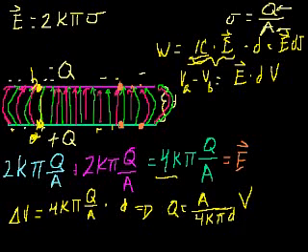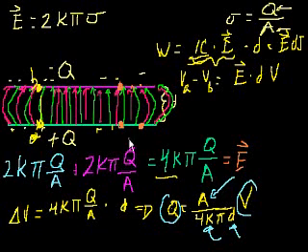Well, what it shows you is, if we assume that the area of the plates isn't changing, that's a constant. This is definitely a constant. And if we assume that the distance between the plates doesn't change, we see that there's a proportional relationship between the voltage and the combined charge in the plates. And that's interesting because, before doing this, maybe voltage is somehow proportional to the square of the charges or to the square root. But now we know that it's directly proportional. And actually, this term right here has a name, and it is called capacitance.